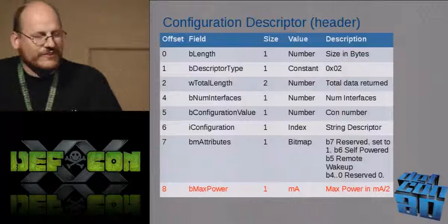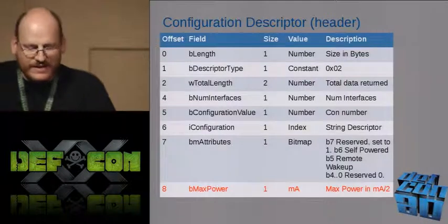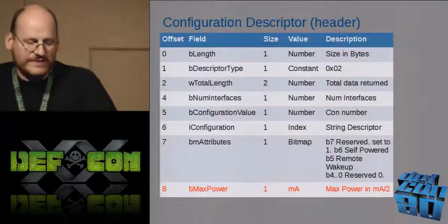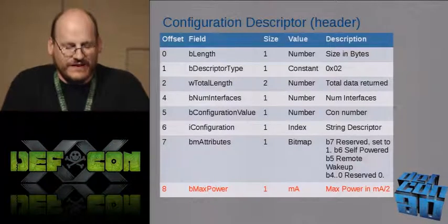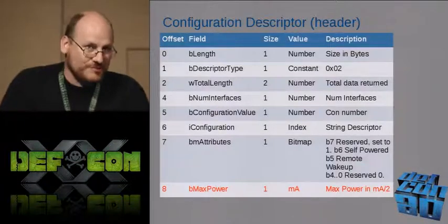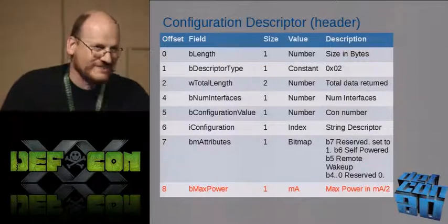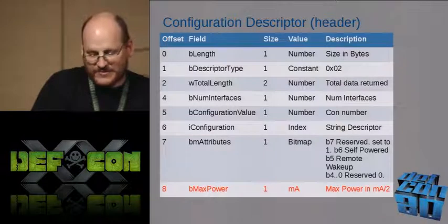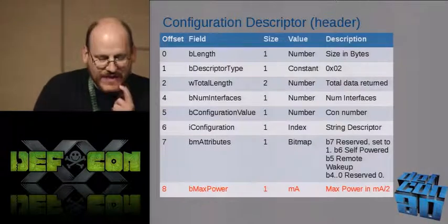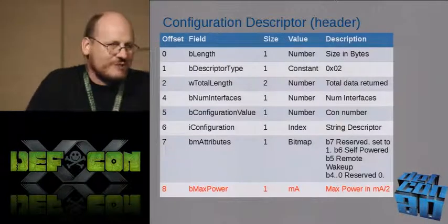So this configuration descriptor is gotten next. And again, it starts with the length. And then the type, it's type 2. They're real creative, right? 1, 2, etc. And it gives you some information. The last bit that it gives you is the maximum power.